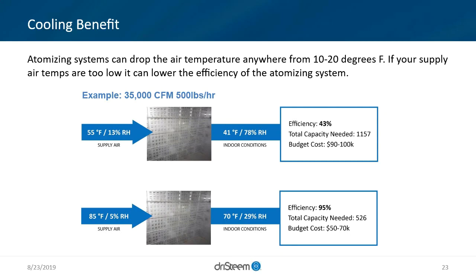But as we look at this example and talk about efficiencies, if we're looking at the same airflow, air volume, and requirement for humidification, with a supply inlet of 55 degrees Fahrenheit compared to 85 degrees Fahrenheit, like for like throughout, we're really looking at the evaporation efficiency. Warmer air can hold more moisture, from a grain perspective, from pounds of water in the air.